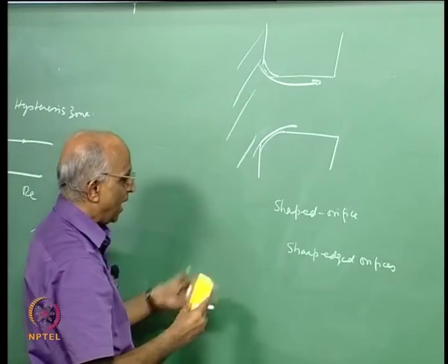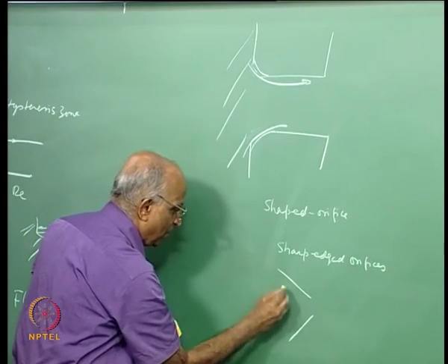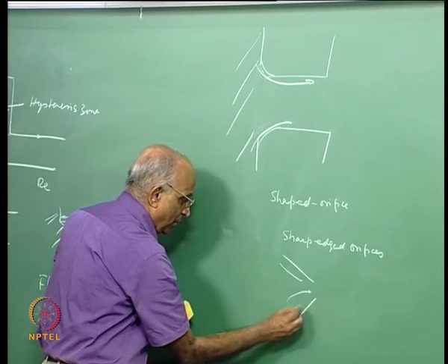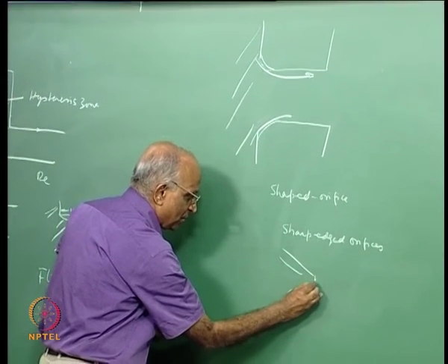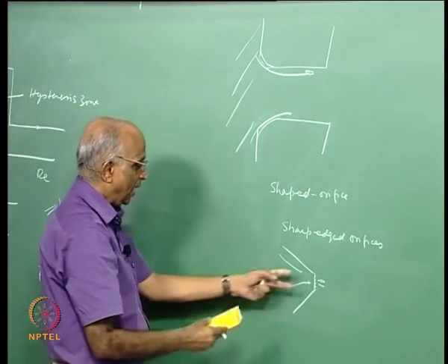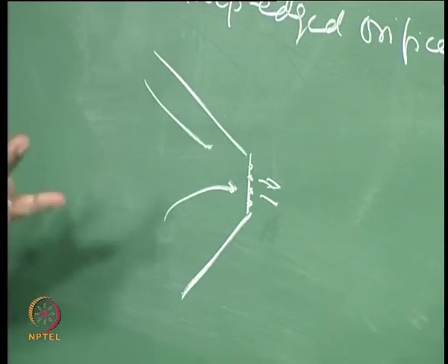That means we have a manifold in which part of the manifold you admit fuel, part of the manifold you admit oxidizer. You have a series of orifices through which oxidizer flows and fuel flows, and that is how we make a showerhead injector.